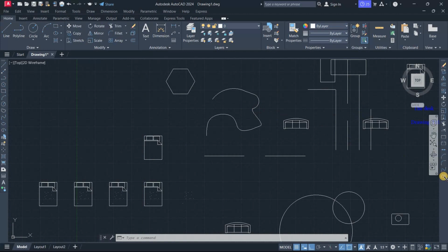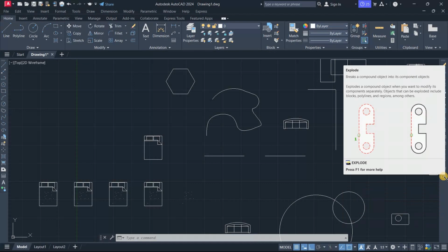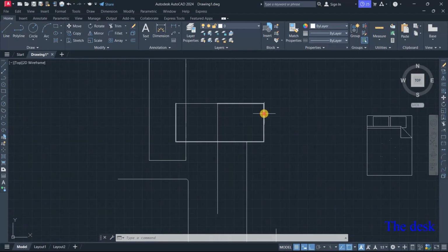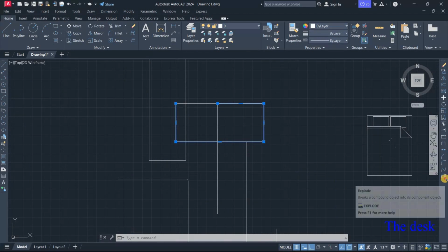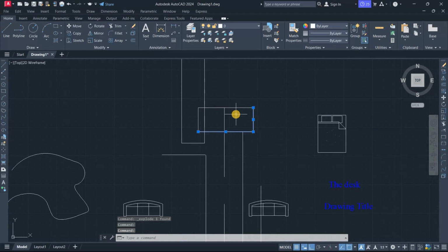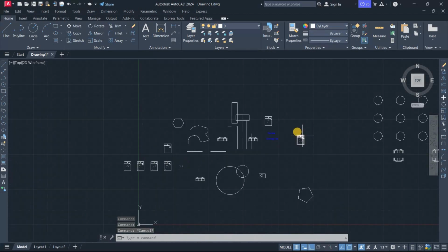All right. So lastly, we go to explode. This will break a compound object into separate parts. Let's say we had a compound object of this when we selected these chains. Of course, if we initiate the explode command, having selected the object, those objects will be separated into different parts as well. The same applies if you want to break a block.